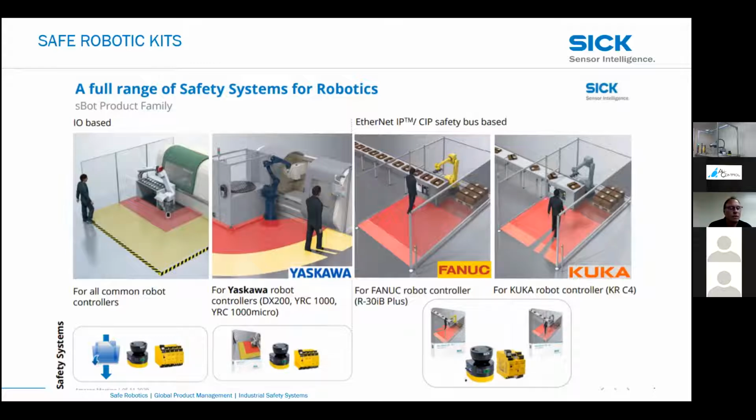We call it generic because it gives you the very standard outputs that you would need on every robot: a slowdown mode, a pause or a stop mode, and an emergency stop mode. Those would be your 3 different modes. In your pause or controlled stop, that would be your automatic restart, where somebody walks in, the robot gets a signal to slow down, then they get closer and it stops. And then when they back out, it speeds back up.